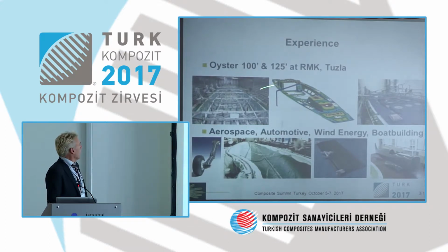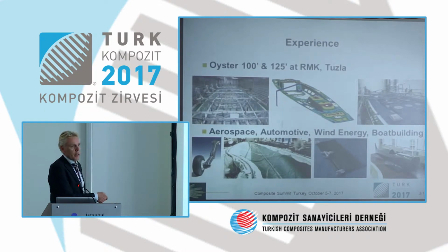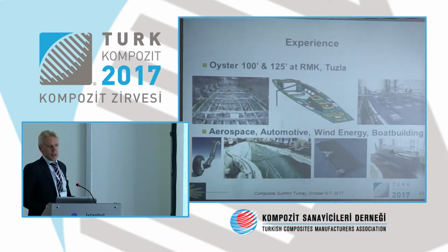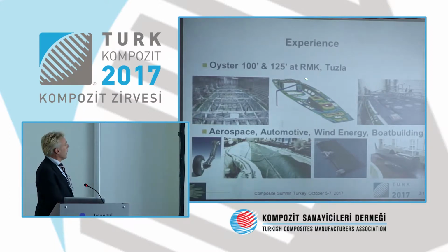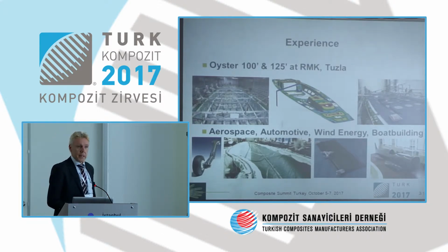So a few pictures to show the experience we already have with infusion. So we did the Oyster 100 and 125, like I mentioned. Here you can see, I hope the pictures are clear enough, the layout of the injection, and you can see it's a very complex set of a lot of tubing and venting points. Here is an image of the flow analysis we did for the deck of the 100-footer. And here you can see the preparation of the infusion for this deck.